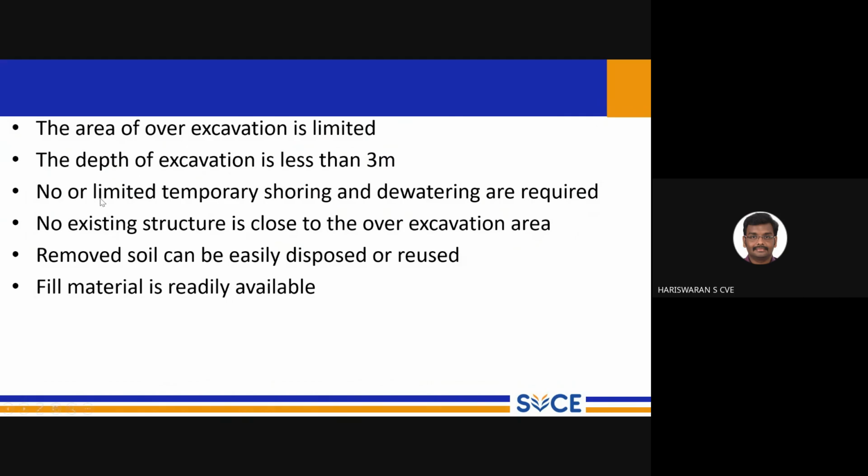So no or limited temporary shoring and dewatering is required for this case. No existing structure should be near that area. Otherwise, when we go for excavation, the lateral pressure exerted from the structure may be exceeded, and ultimately that excavation also collapses. The nearby structure also starts to lean, or it leads to differential settlement. That is a major problem. We are supposed to take care in the right way.